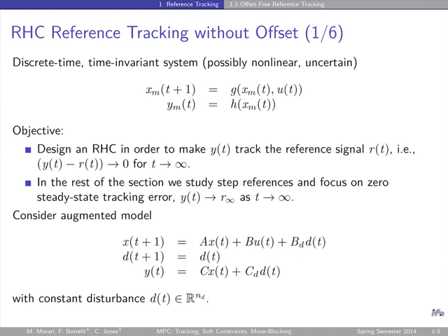And so we assume now that the set point is constant, as I mentioned. The first thing we do toward achieving this is we choose a linear model, and the linear model is the same linear model that I have here. So we have x(t+1) = Ax(t) + Bu(t). That's our linear model. But now we add something to that model. We add a disturbance, and that disturbance is this disturbance d here, and what we also added down here. And we assume that this disturbance is constant.